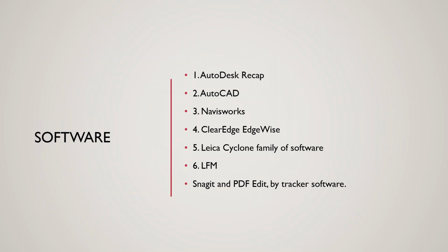AutoCAD: you can pull these laser scans into AutoCAD. I haven't shown it today. If anyone wants to see more, you can contact me. But AutoCAD in the past 5 years has gone very, very far. It's very simple to pull a point cloud in. There's a button to do it, and it takes about a minute. Navisworks is a great way to view your point cloud with your other CAD drawings, and you can use a lot of different CAD versions and versions of models, BIM and such.